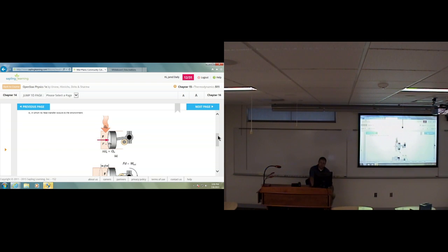Here is one version, a very simplistic version of a heat engine. You have heat coming into a piston filled with a gas that is sealed off, and on the end of the cylinder, there's a piston. So this is the cylinder, this is the piston. As you heat the gas, it expands according to the ideal gas law.